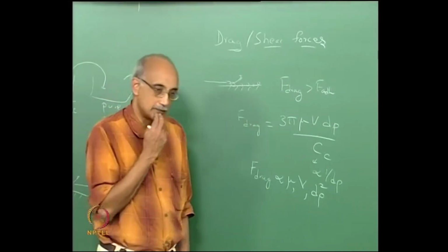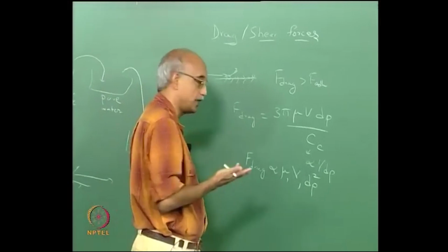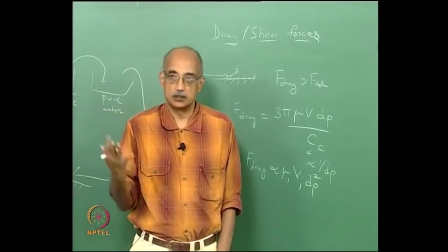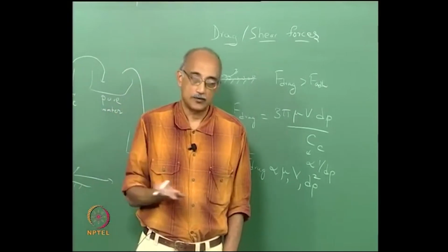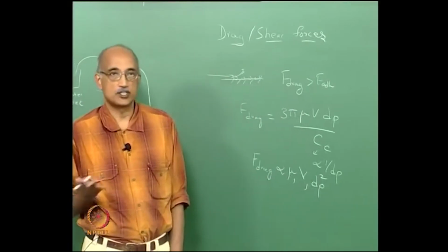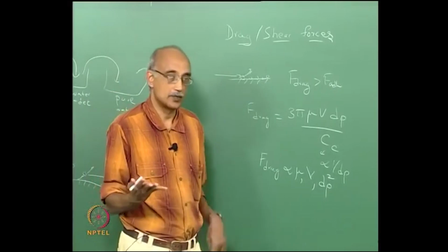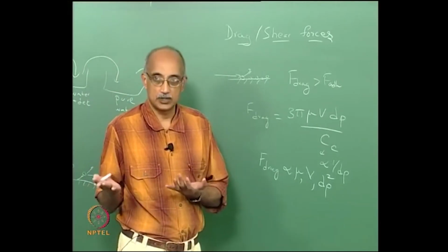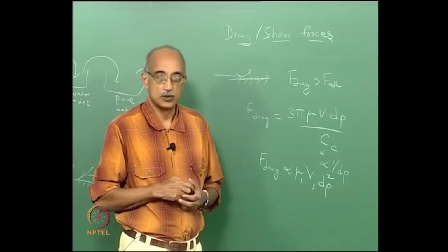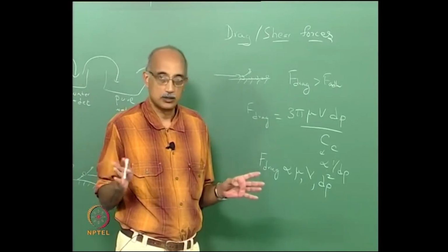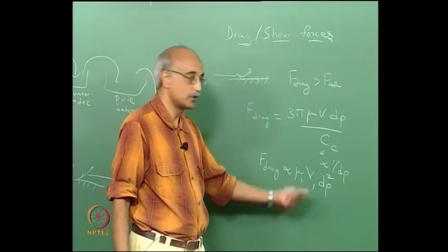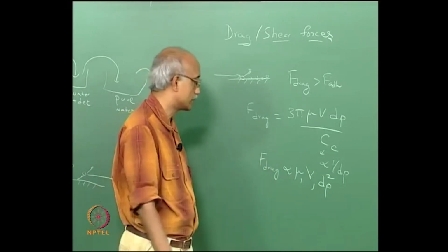What are the implications of this? Well, the first implication is a higher viscosity fluid exerts greater force, and in fact that is why water is a much better cleaning medium than air, because the viscosity of water is about 55 times the viscosity of air. So all other things being equal, if you do the shear cleaning with water, it's going to be 55 times more aggressive.